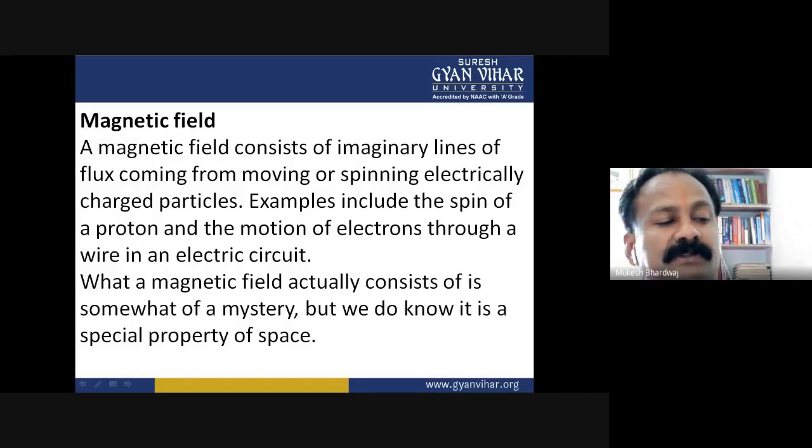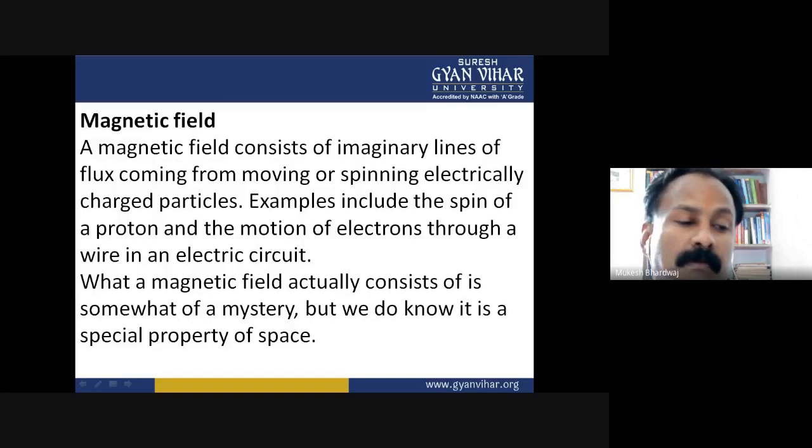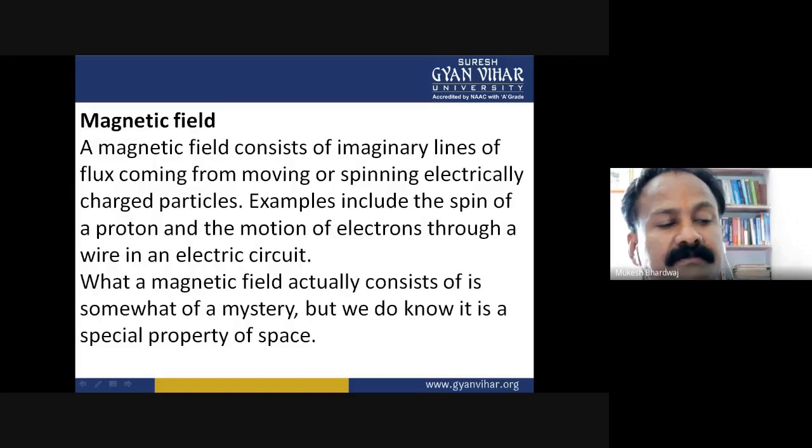We have discussed Biot-Savart law and Ampere's law in terms of H, or magnetic field intensity, but these laws can also be put in terms of magnetic flux density, that is B. During calculation of magnetic field intensity, the surrounding medium is not taken into account, while in the calculation of magnetic flux density, the medium needs to be considered. The relationship is put in the form B equals mu H, where mu is the permeability of the material or medium.